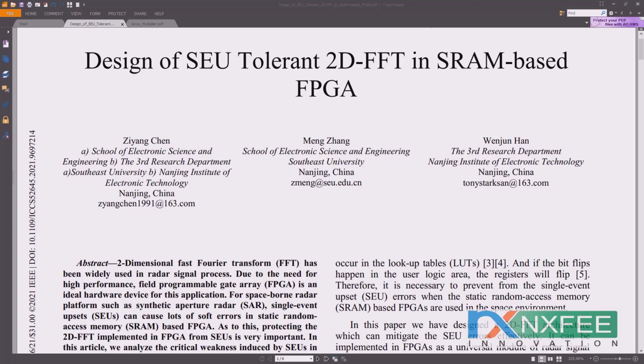In the proposed approach, instead of radix 2, the proposed architecture builds the SEU tolerant 2D-FFT utilizing a radix 4 design architecture to minimize the number of iterations in the 2D-FFT and to minimize the logic with garbage signals. The SEU tolerant 2D-FFT was designed utilizing the reversible array multiplier architecture. This proposed architecture was compared to the conventional array multiplier architecture with conventional full adders, and the performance in area, latency and power in the Xilinx Vivado Artix 7 FPGA was demonstrated.